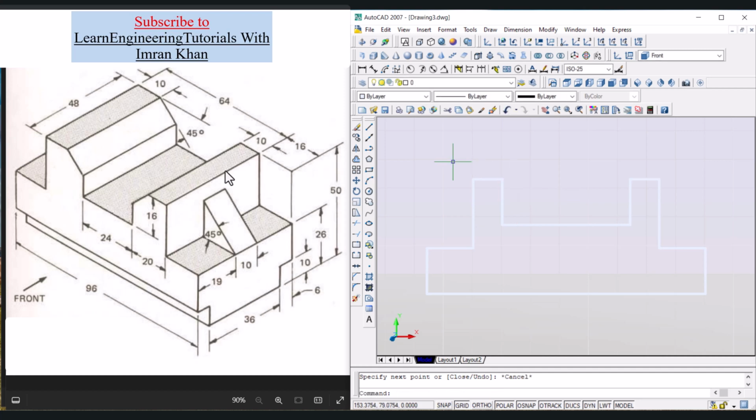Press escape. Now we can see that this angle is actually 45. So here we can draw a line from this point at an angle of 45. We can give any arbitrary value. For now this value might be 15, tab, minus 45, enter. Press enter. Do the same on this side.